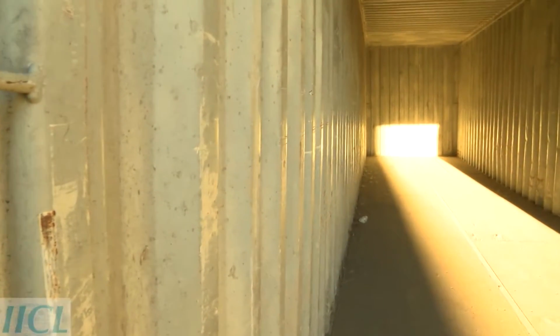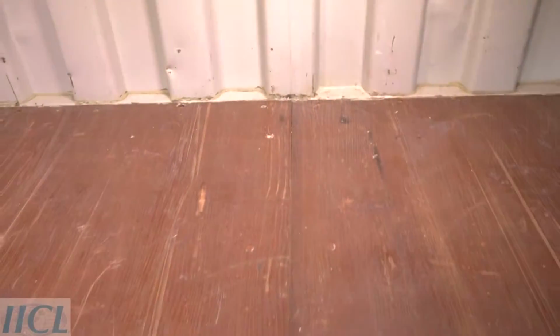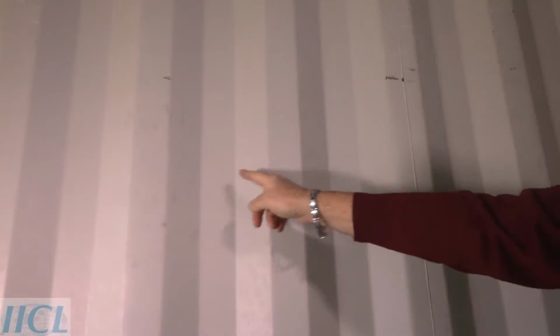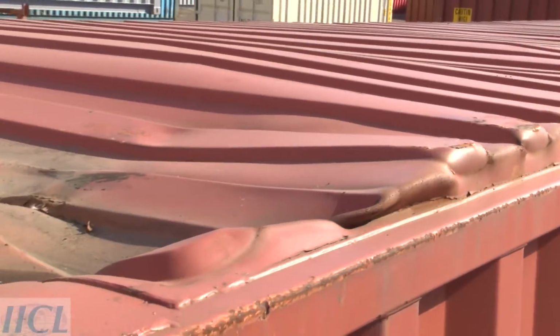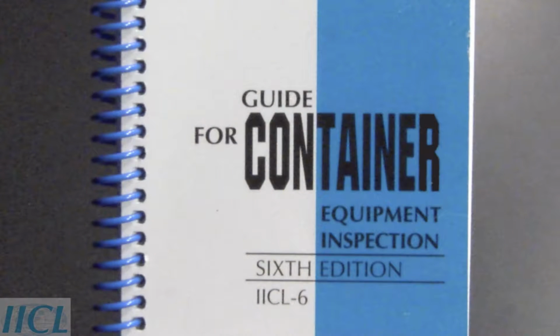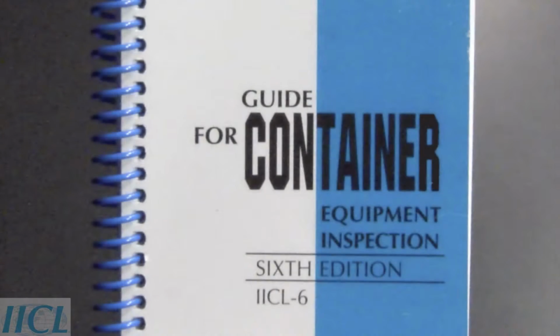The cargo space inside a container, commonly called the cube, is defined by the planes of the floor surface, the standing corrugation faces for the sides, front, and door, and the plane formed by the top surfaces of the top side rails. Certain criteria limit the amount that damage can protrude into the cargo space or cube of the container. These criteria are commonly called in-cube criteria, but like many out-of-ISO criteria, the IICL has respecified them as reference dimensions that can be easily measured with a string line and scale.